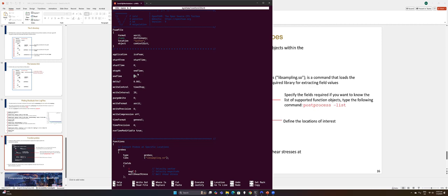If your time is shorter than the time it takes to complete one length of the pipe, then your solution is not converging. Although the numerical solution could converge, what you have hasn't actually run to the outlet. So make sure that the time is long enough to cover from end to end based on your conditions as well. Anyway, let me just put this as maybe 5 so that we can proceed from here.